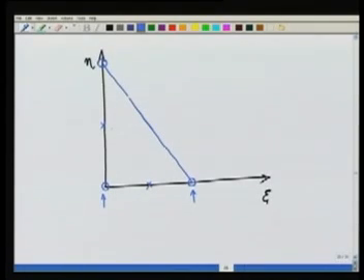Now what we do is we draw the line parallel to the base through this middle node, and the line parallel to the base through this middle node. This will cut at the middle of this edge, and as we have said for these two edges, similarly on this edge also the projection of the quadratic should be a quadratic. So this edge also requires a third edge node to be added. So you see that in order to have the quadratic, at least on these edges, we have to have these 3 new nodes added. So why not go ahead and add these 3 new nodes?